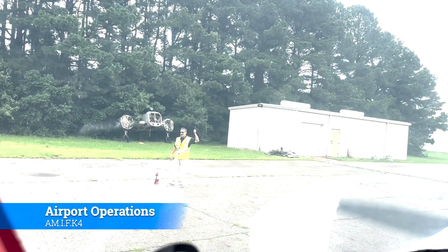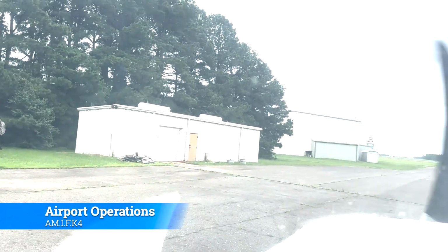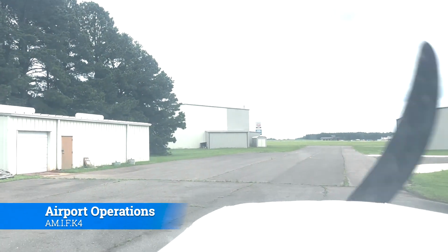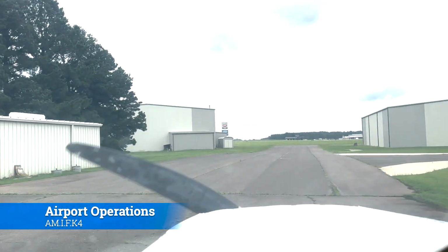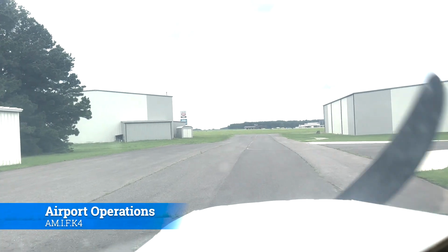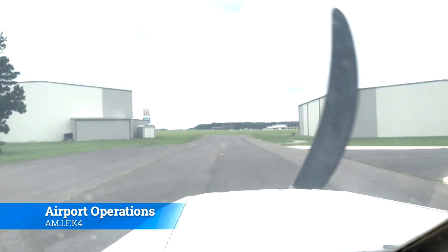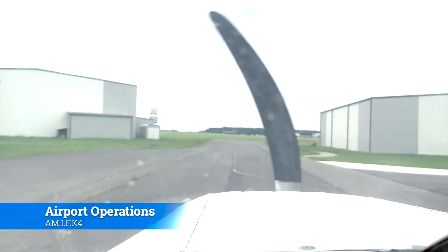All right, so as we crank the aircraft and we taxi off, there's a couple of rules of the road that we want to make sure that we stay on top of. First off, stay on the taxi line if you're on a taxiway or in an area. The best way to do that is to look down the taxiway, and the yellow taxi line should go in between your feet. You should imagine yourself sitting on top of the taxi line everywhere you go. As it turns, you turn with it, and you keep it in between your feet. That will keep the aircraft centered on the taxiway.